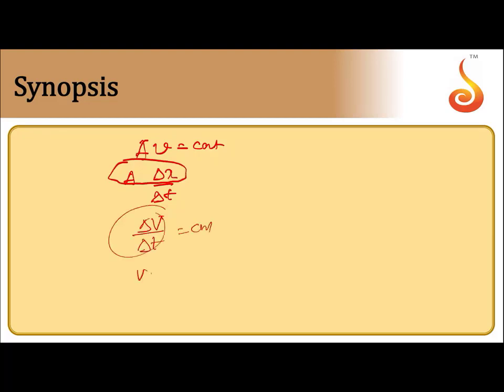It tells you volume flow rate. So this is nothing but volume flow rate. So equation of continuity can be interpreted as mass per unit time is constant or volume per unit time is constant. Any of these two representations is perfectly fine. If you are talking of constant density, then volume flow rate remains constant is a better description of the given situation.